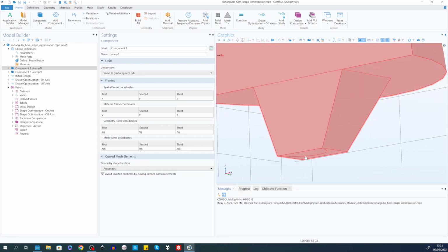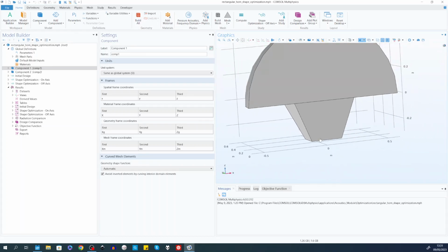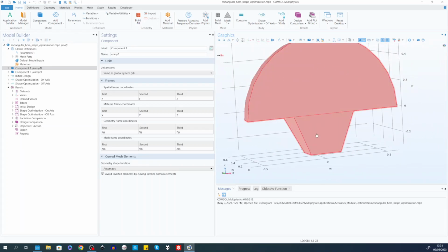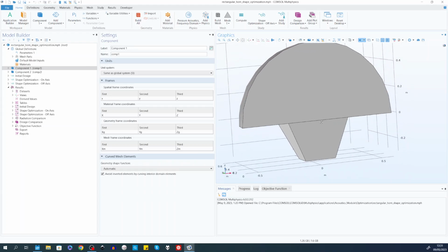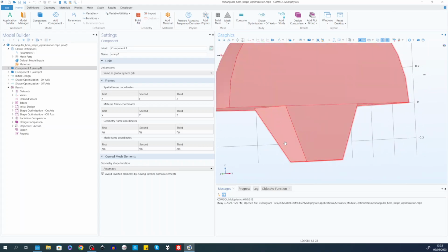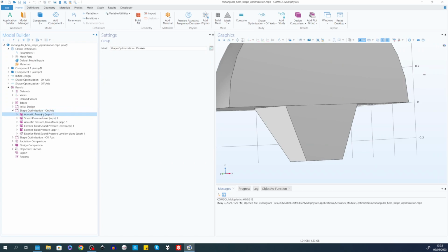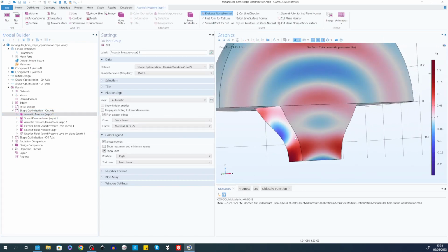So you have a driver down here, and then you have some geometry here leading out to the outside world, and you want to generate a flat sound pressure level somewhere, and then you can set these boundaries free and manipulate them and warp them, and end up with different shapes that we can see here, that the simulation has been set up in a way so that it's allowed to change the original geometry.